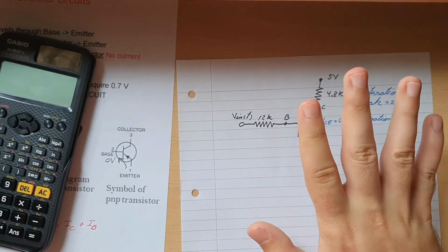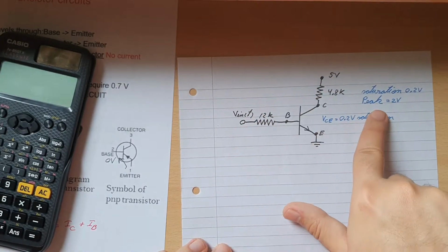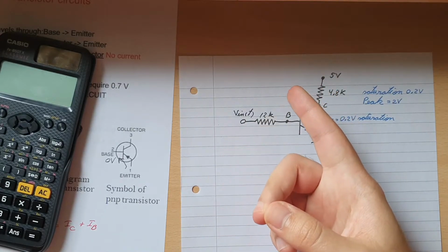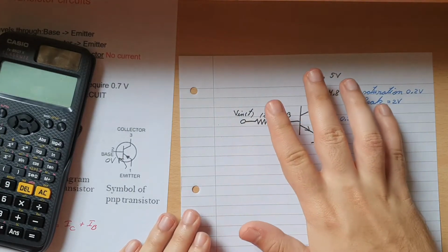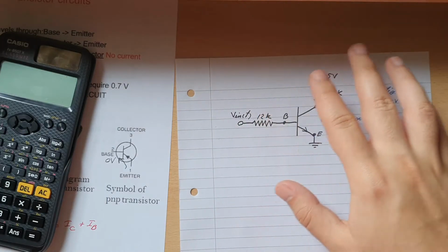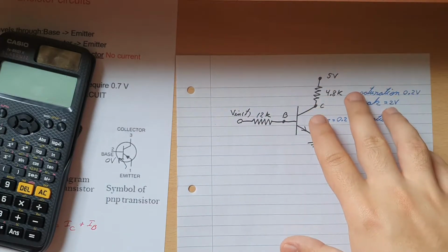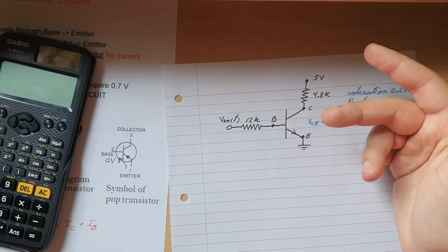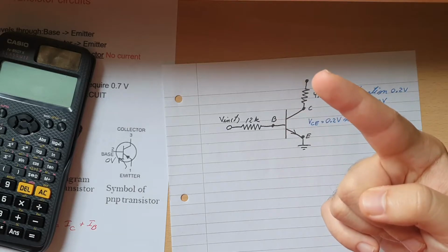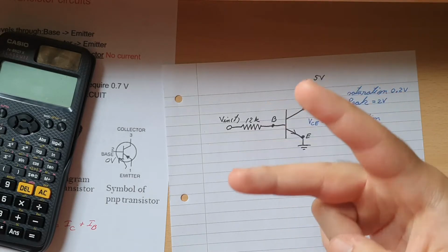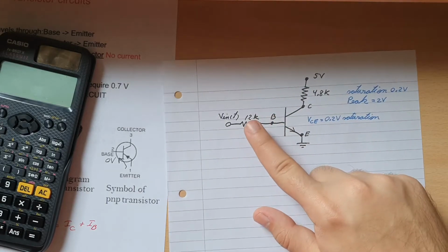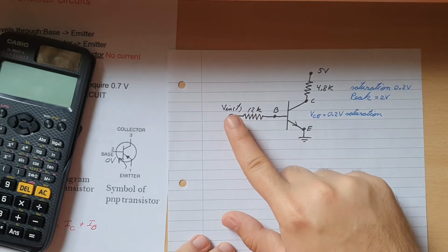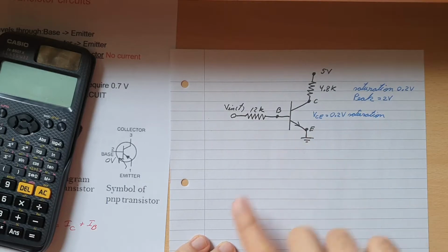But the important thing is that with the peak 2 volts and the AC source, the reason why we can do it like this here, and I can't do different, more complex AC circuits or amplifiers, is because again, it's only resistors, so it doesn't really change anything. You don't really need to change it to the RMS value, and you don't need to worry about the phases because the resistor has a phase of 0 degrees, so it just stays the same. So there will be the same phase on the input as the output.